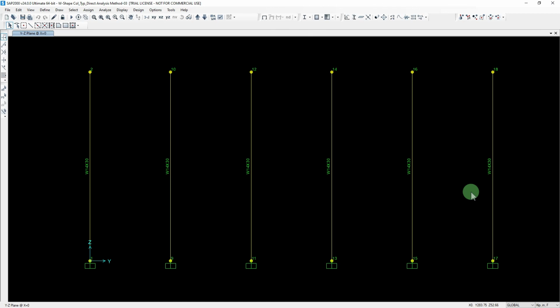For the 14 sections, the W14s, that starts at the 14 by 43. You'll see going up from there that the rest of the sections are pretty much boxed, or they start to get to a situation where the flange is actually outgrowing the depth.